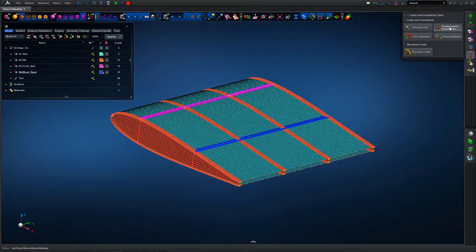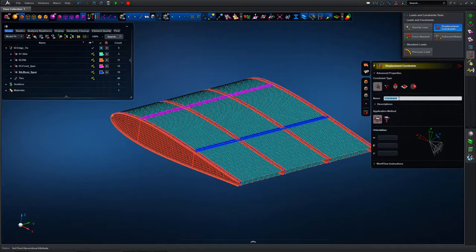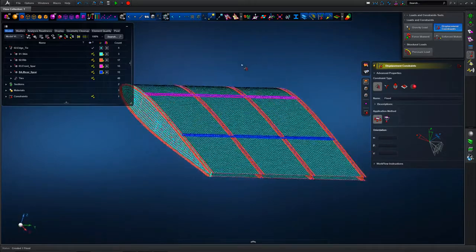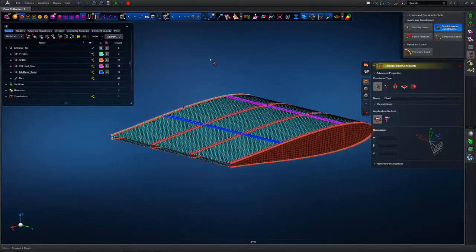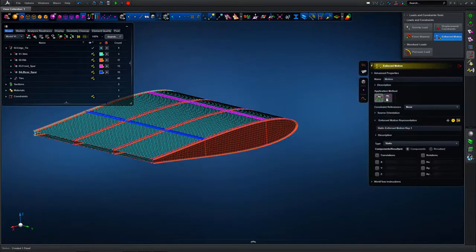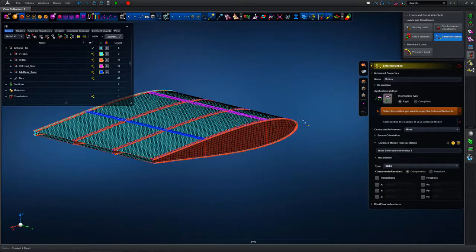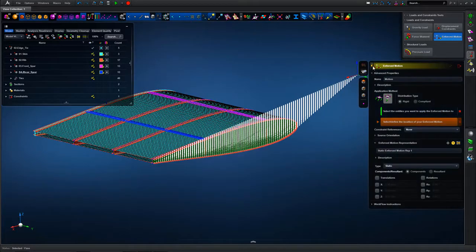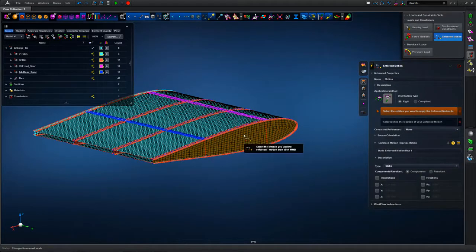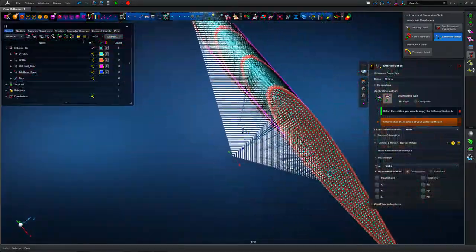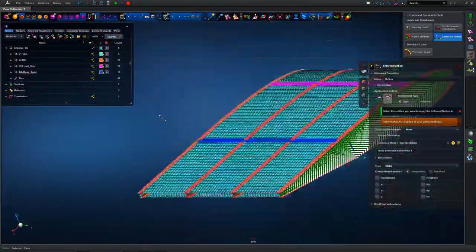Now the model is complete, so we're going to apply some simple loads and boundary conditions. So the inboard end of the wing box we have fixed, so all degrees of freedom clamped in space, and then we're going to put an enforced displacement to act on the outboard rib web, as it were. So specify the region where the displacement is going to act. In this case, we're using a rigid connection, so the whole of that region will see the same displacement.